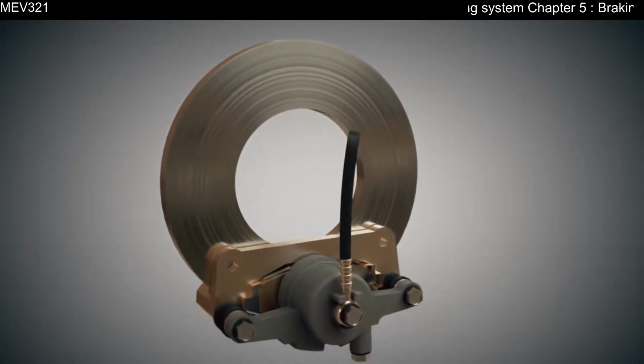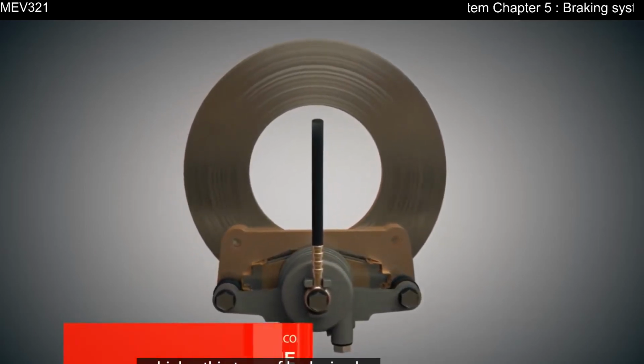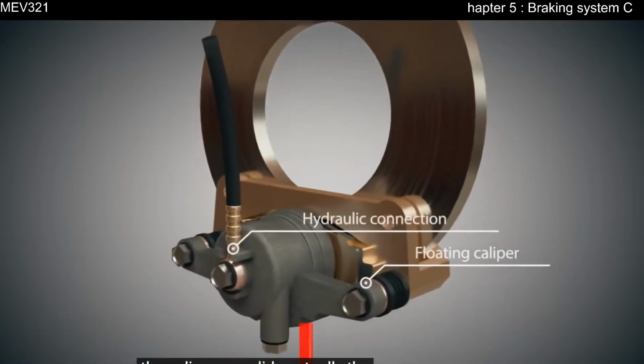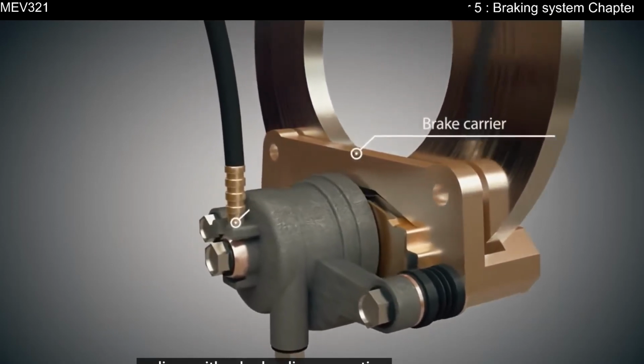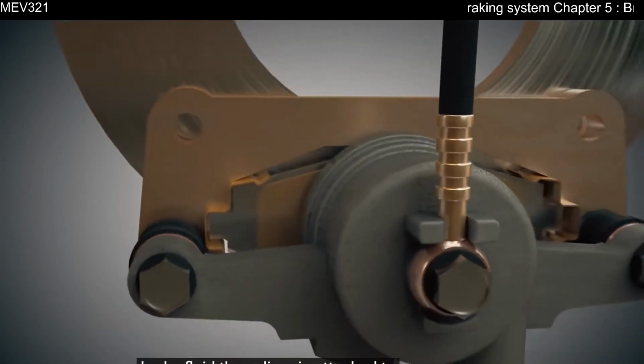Floating caliper brakes are used in many vehicles. This type of brake is also known as a sliding caliper brake because the caliper can slide axially. The floating caliper brake is composed of a caliper with a hydraulic connection through which the brake is supplied with brake fluid. The caliper is attached to the brake carrier.